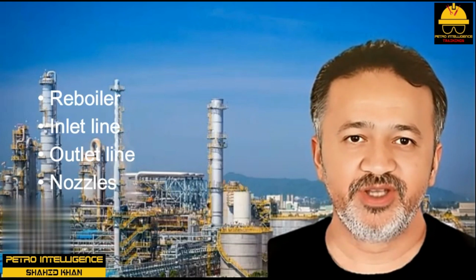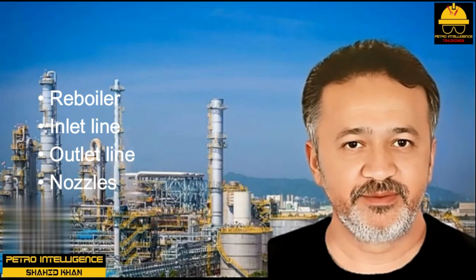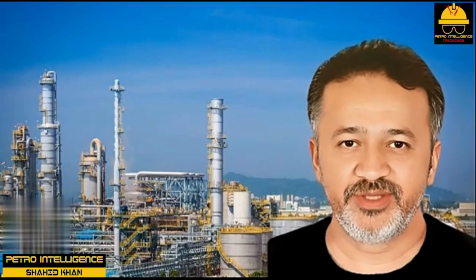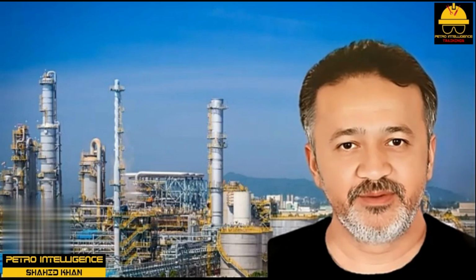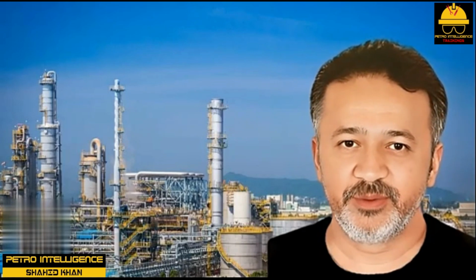It is consumed in overcoming the frictional losses due to the flow in the reboiler: inlet line, outlet line, nozzles. If these frictional losses are less than the 4.7 psi we have calculated above, then the inlet line does not run liquid full. If the frictional losses are more than the 4.7 psi, the reboiler draw-off pan overflows, and flow to the reboiler is reduced until such time as the frictional losses drop to the available thermosiphon driving force.